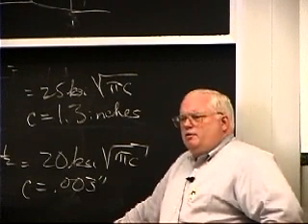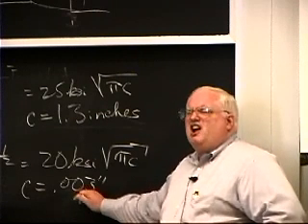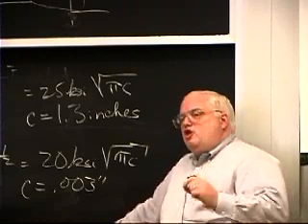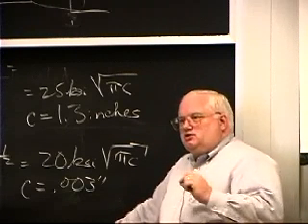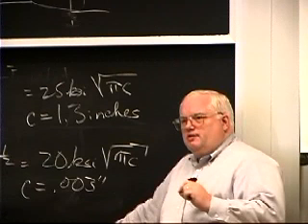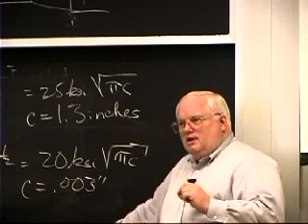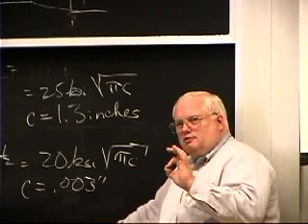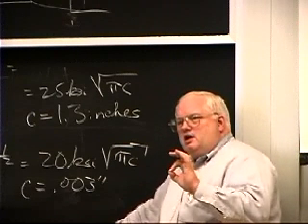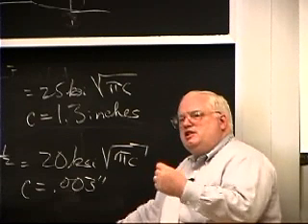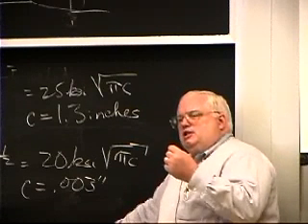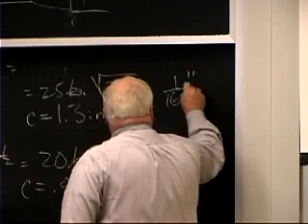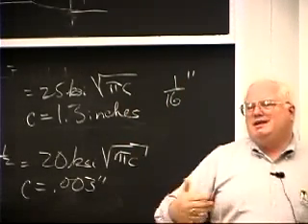And he claimed that by ultrasonics, he found a reference that said you could find flaws with ultrasonics as small as 1/1000th of an inch. That's absolutely true. Under absolutely ideal laboratory conditions, if you know they're there, you can find flaws 1/1000th of an inch in size. I mean, you can get a signal, a blip, okay? But if you go and do a study of what people find in the real world, the smallest flaw that people typically find with any reliability is about 1/16th of an inch. A lot of times, maybe you should only be saying 1/10th of an inch.